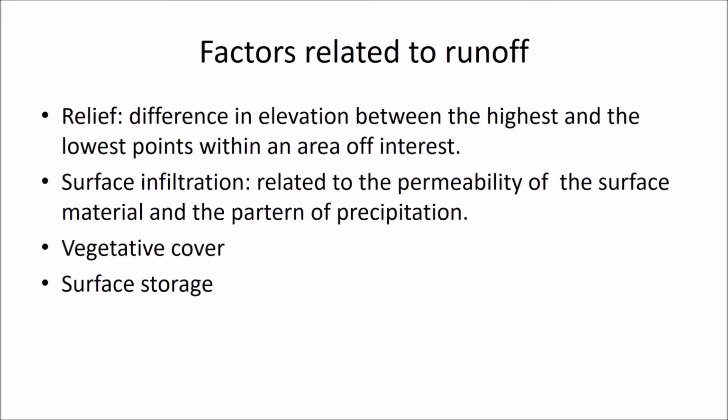Okay, talking about the runoff, the runoff may be related to some factors. It can be related to the relief, the surface infiltration, the tree cover, and the surface storage. The relief is the difference in elevation between the highest and the lowest point within an area of interest.